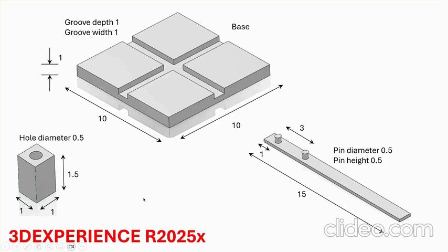Okay, and what I was talking about, you can attach a motor here to one of these, for example, and make the rod turn continuously about one of the blocks, or you can attach a motor to this one, etc. Or you can push this prismatic joint, one of these blocks along the track. Eventually, the bar will rotate and traverse an ellipse.